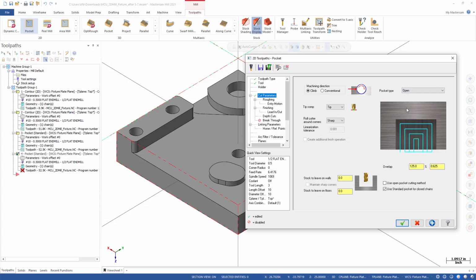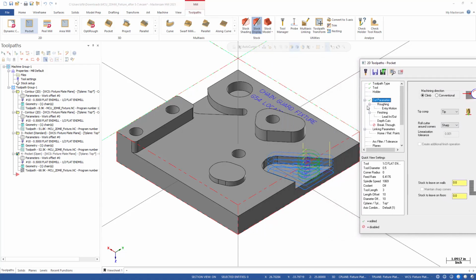And here's where we can choose an overlap on which amount it'll go over, and that can be a percentage of the tool like we saw before. Without anything else, let's hit the Preview Toolpath button. We'll zoom out so we can see how this toolpath is working. As you can see, it's still helicing in, and then it comes to the final depth, and it does its final pass.